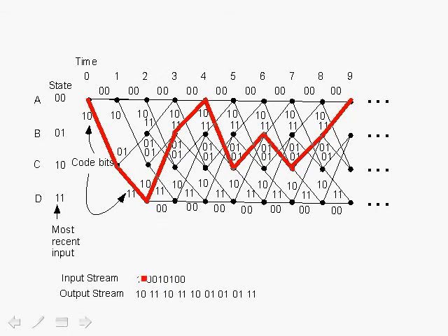Now this particular input sequence, recall that we always start out at state 0, 0, and purposely this input sequence we have at the end 2 zeros, and that corresponds to the length of the shift register, which was a 2-bit shift register, and this way we always flush out the shift register and always return to state 0.